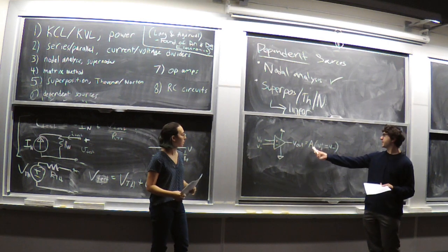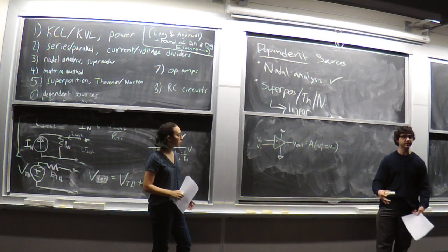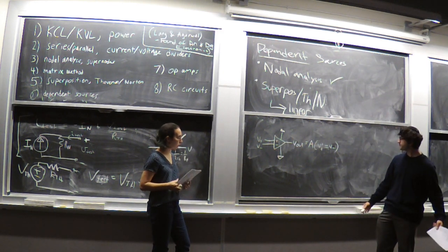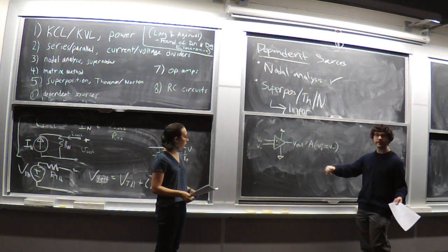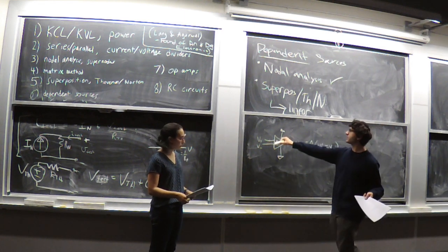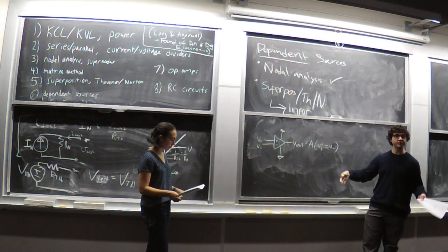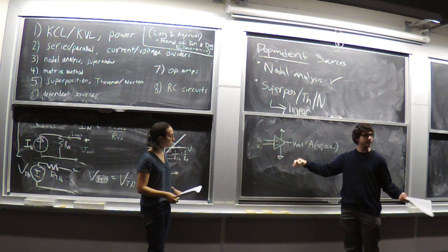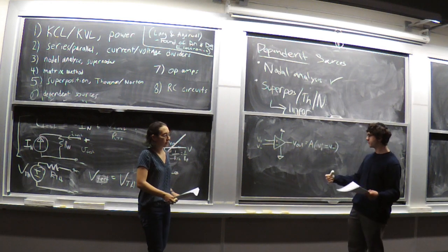So one key to op-amps is that A is generally enormous. We like to think of it as infinite. In practice, it is not infinite, but it is very, very large. And so the problem we would run into is, if A is like 1,000,000 or something, and V plus minus V minus were like a volt, we would be trying to get 1,000,000 volts at the output, and as Hannah said, it would just cap to whatever our highest voltage power supply was. So that's not particularly useful, at least as far as we are currently concerned.